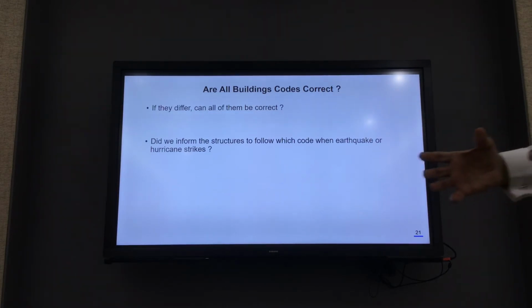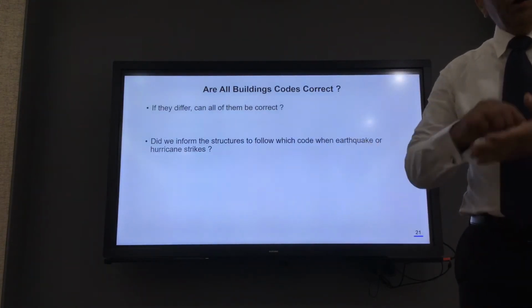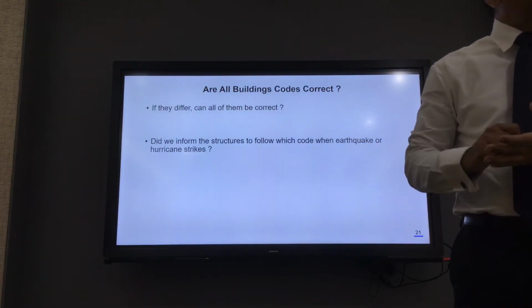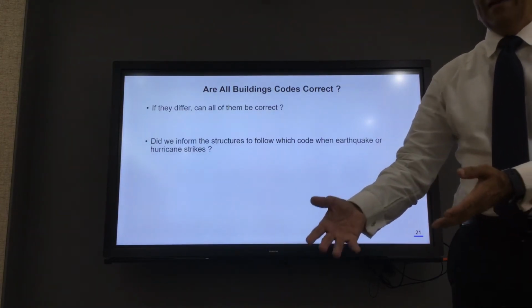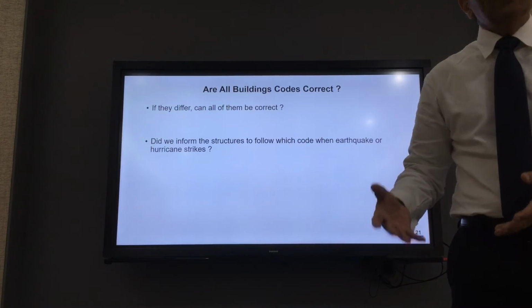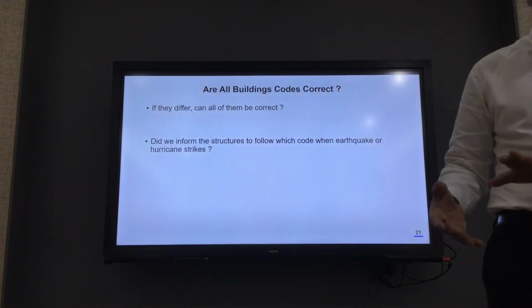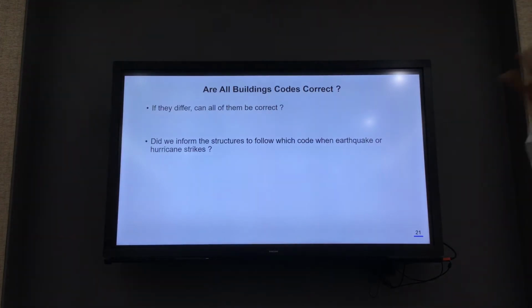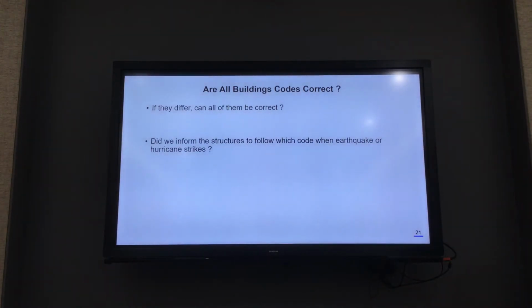If you put 4 bars, whether somebody just estimated 4 bars or you did a million calculations to arrive at the 4 bars, these are 4 bars. The structure is going to behave based on the 4 bars on site, not on how we arrived at it. Correct or not correct? So for that reason, there is no distinction between the codes when the structure performs during a hazard.